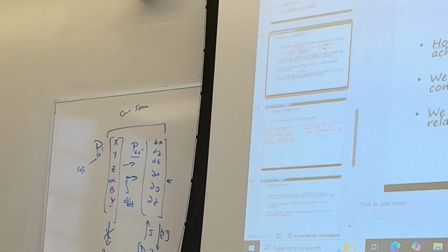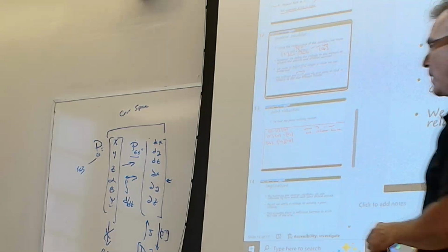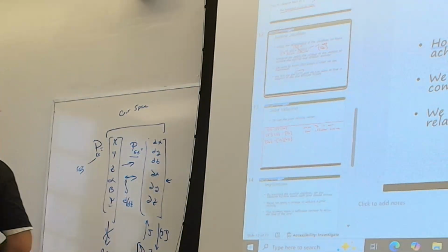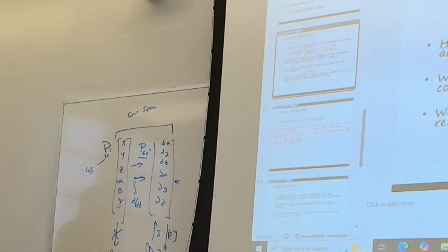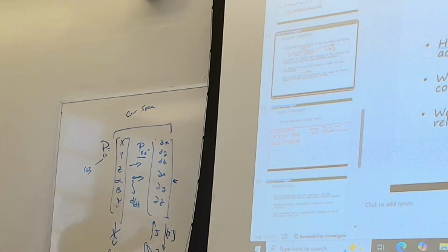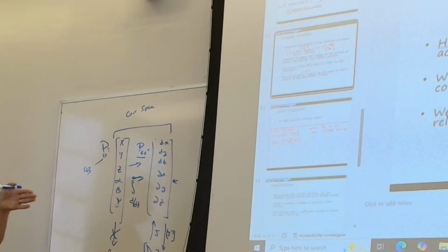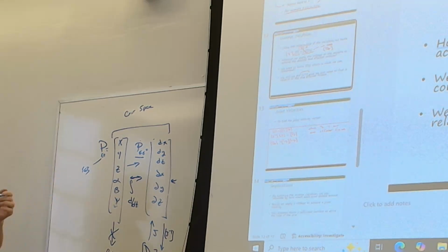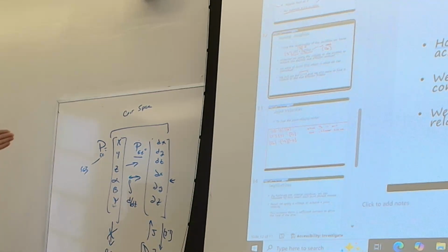But the theta dots combine together to give you what's called our heading. So the differential velocity of the VL and the VR, when you change the velocities, you affect the heading angle, which is the same thing we've got over here. This is kind of like the heading angle. And so those changes, you might have gotten theta L and theta R, or displacement L and displacement R, to be what you needed them to be. To get those where they needed to be, you adjusted the velocities.